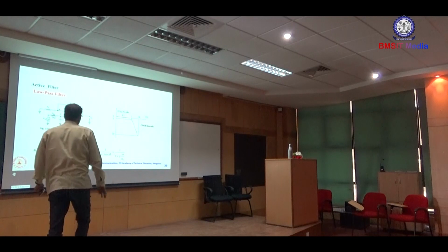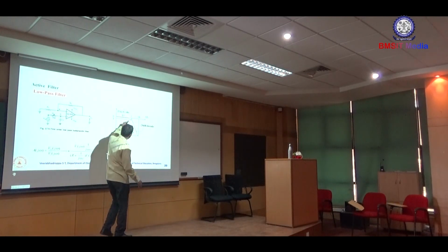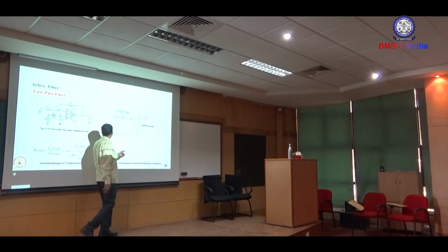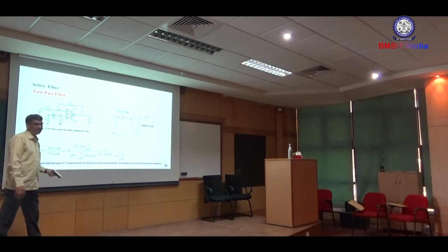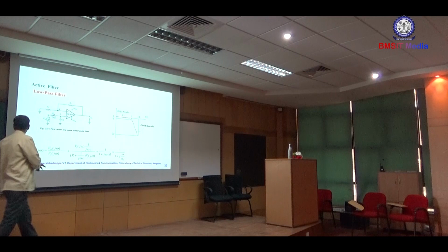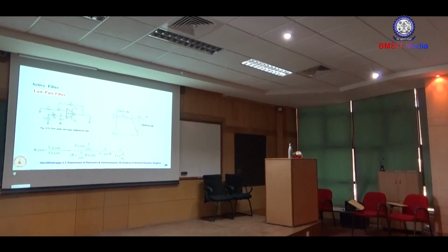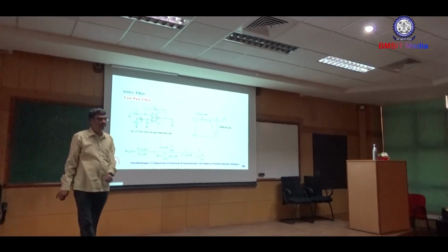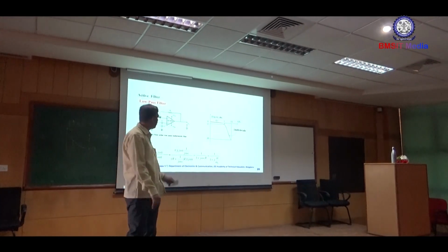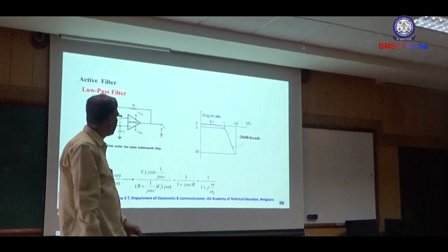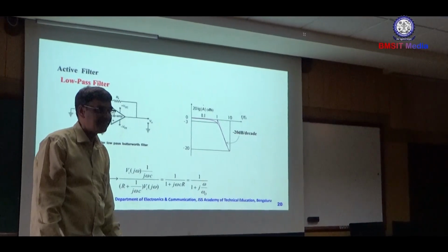And then there is the question of at what rate it decreases. The next question arises. I am not going to derive this. Normally, this is a first order low pass filter. Normally, the order of the filter determines the decay in the transition region, which decreases at the rate of minus 20 dB times N, where N is the order of the filter. In a second order filter, the roll off rate is minus 40 dB. Why? What is the indication of my negative sign here?